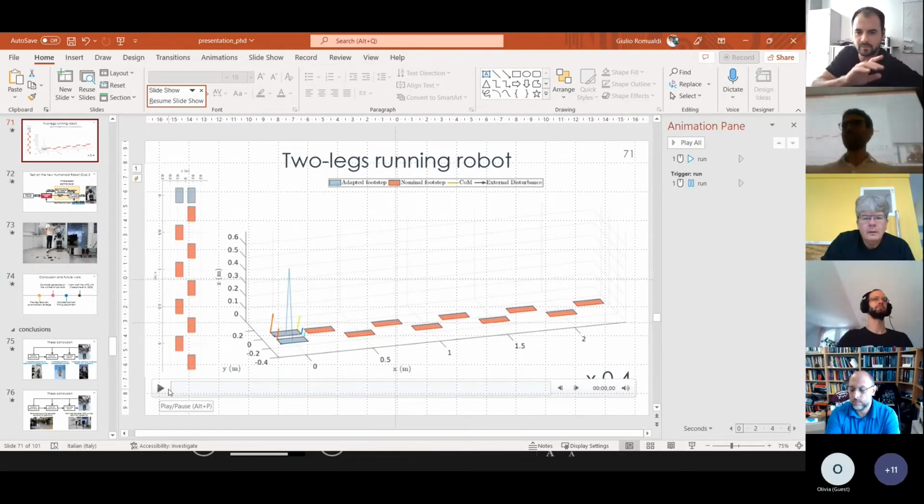So what we see here in red are the nominal footholds that you plan with your simplified model. Now you run your controller. You get these nominal footholds as regularizer terms into your MPC controller. You're not replanning a nominal foothold, but getting it as a regularizer from outside, from a very old pre-planned setup, and you're doing your MPC. I completely understand your question.